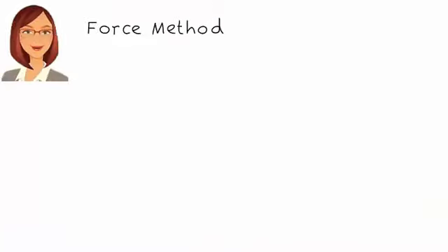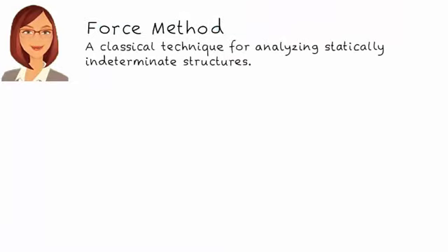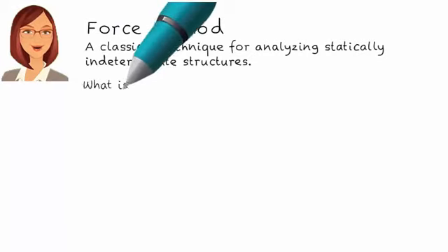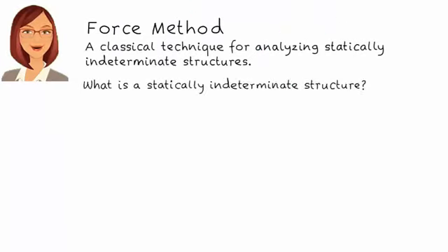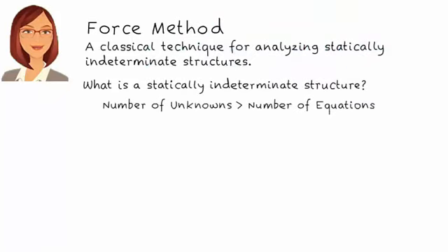The force method is a classical technique for analyzing statically indeterminate structures. Before we get into the details of the method, let's spend a minute talking about statically indeterminate structures. We call a structure statically indeterminate if its number of unknown forces is greater than the number of equilibrium equations.